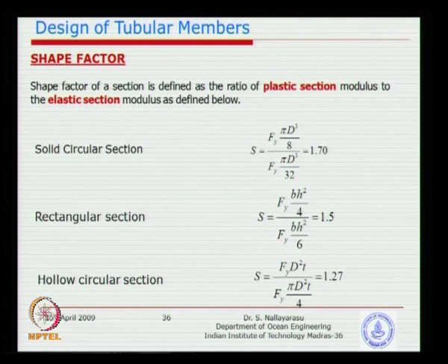So, that is the reason that in most designs we use hollow circular sections, and also they offer alternative advantages: fabrication becomes easy, less heavy, more buoyancy, good hydrodynamic properties. So, using that we try to optimize the design.